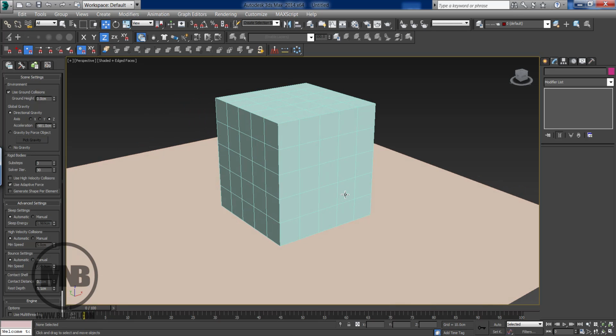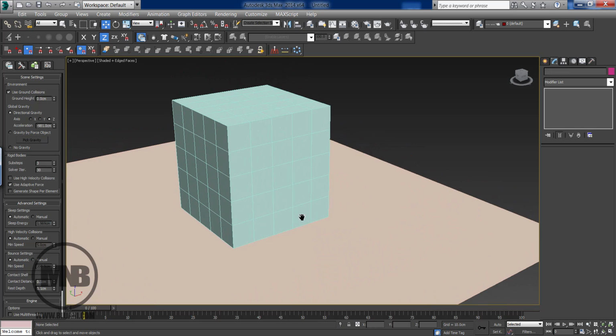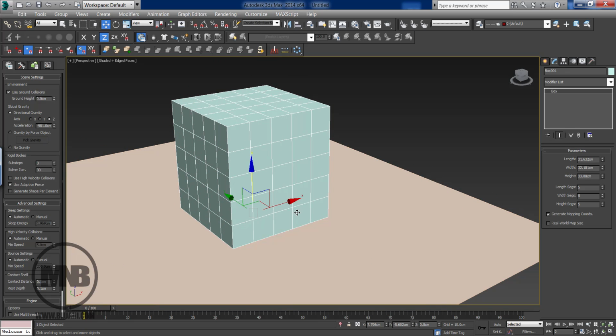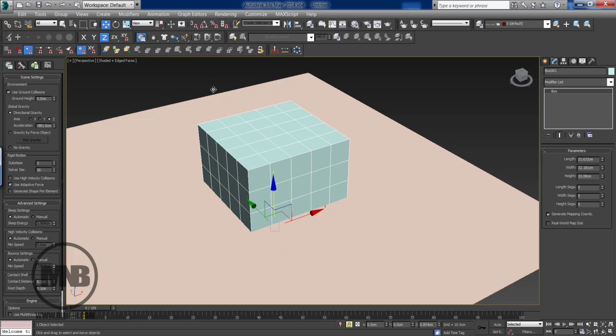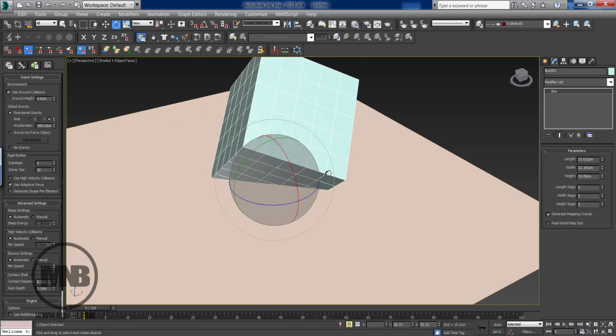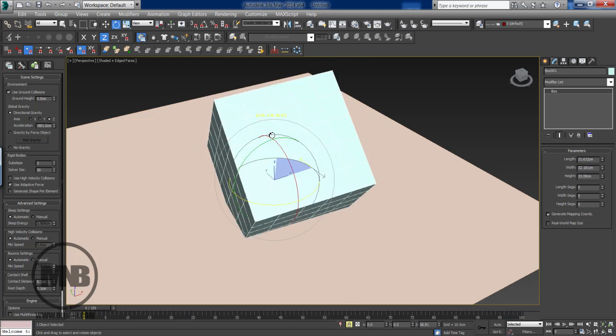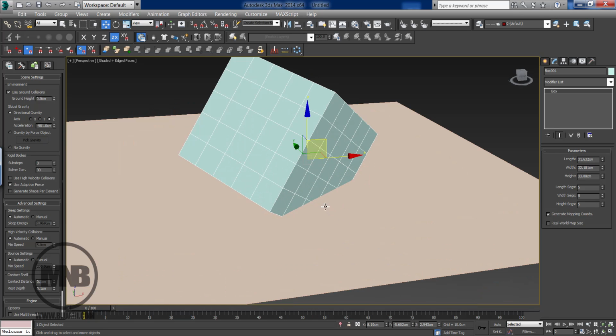And for the last thing I need to mention before we wrap it up, basically a shortcut, which is the spacebar. If you select any object and you press spacebar, look at this lock button in here, it will turn on. And now if I need to select or deselect, I cannot. It's just locked on this object, and using this tool, I cannot move it. I cannot deselect. It's just selecting this object and moving it all the time. Just make sure this selection lock is not turned on. So I can turn it on and off by clicking on it, or just pressing spacebar. Just make sure, sometimes it will come in handy later on.